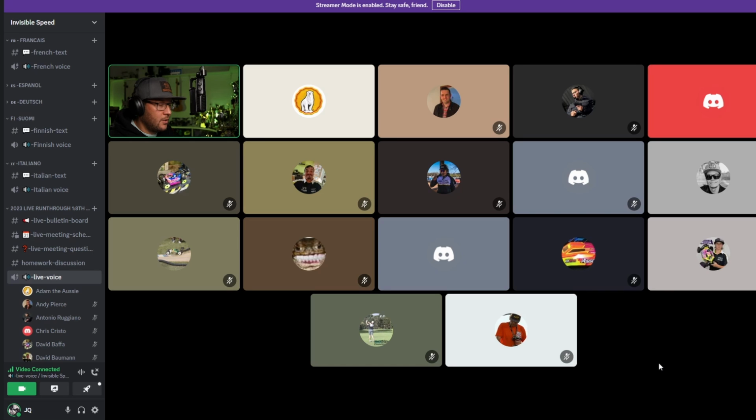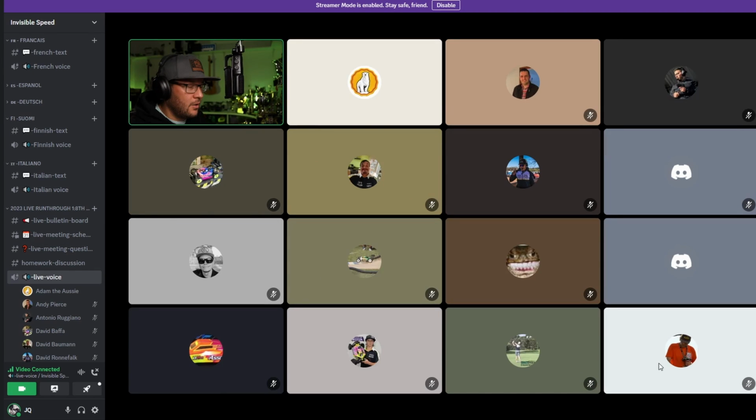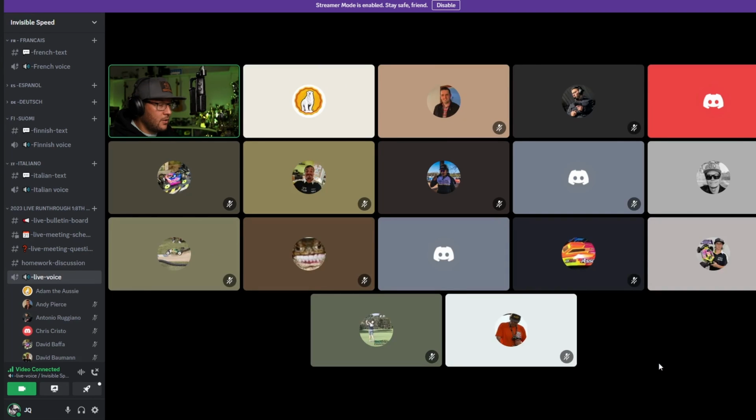Camber change is very difficult to quantify because always when you change roll centers, you're also changing camber gain. So you can't separate the two completely. They always go hand in hand. So the way I think about it is roll centers affect the jacking, so in the track or on the track. And roll centers affect initial versus overall grip. But then camber change affects the sort of maximum available grip.